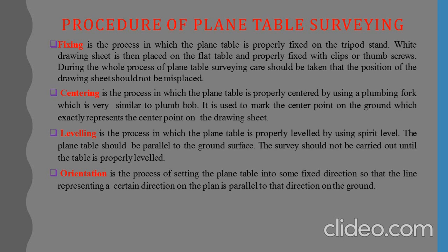And the final procedure is the orientation. Orientation is the process of setting the plane table into some fixed direction so that the line representing a certain direction on the plan is parallel to the direction on the ground.